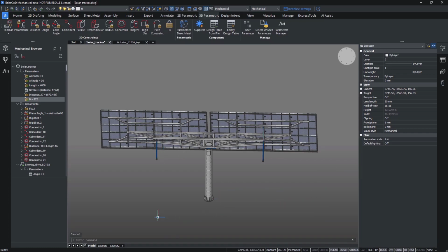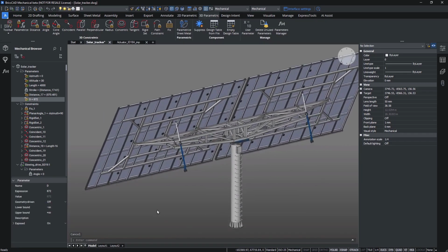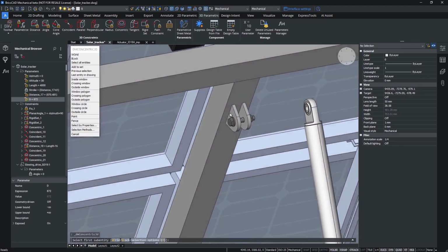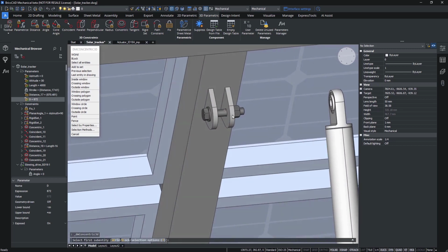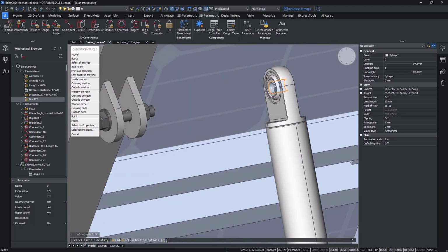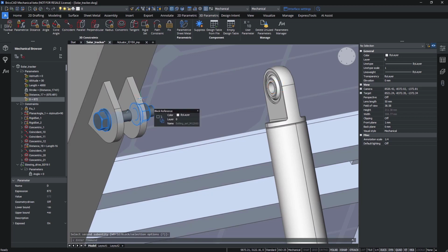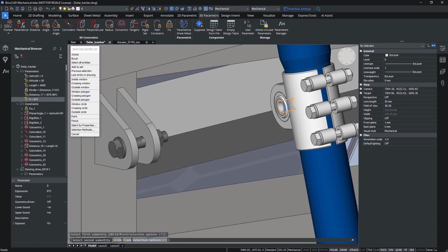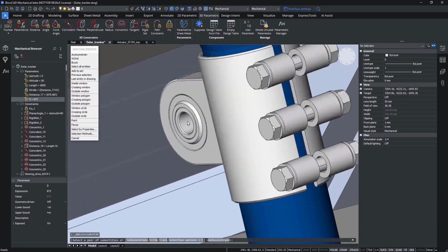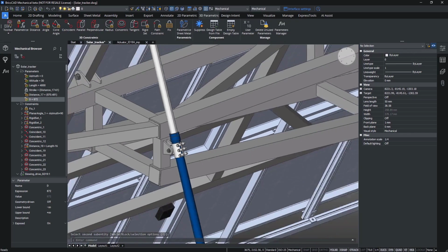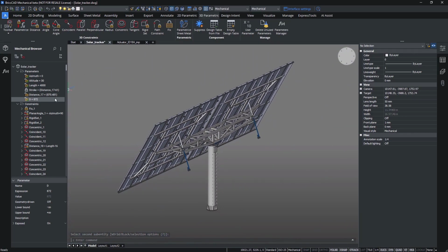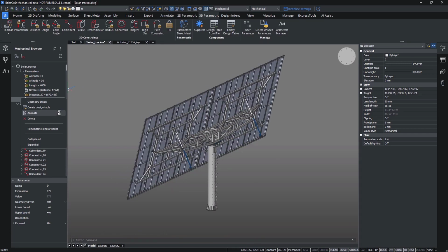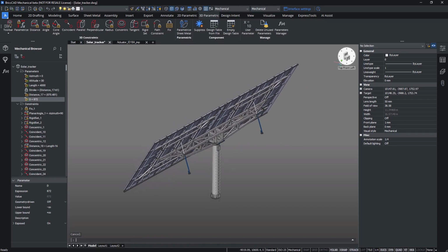My favorite way is to copy-paste, so let's duplicate the first actuator we have just prepared in the step before. As a mechanical block, the actuator maintains the constraint between the subcomponents. Let's add 3 more constraints so our assembly is fully defined. On the axis, once again, and 1 more for the faces. Here we go. The integration of the actuators is complete. We can play the kinematics to see the new results.